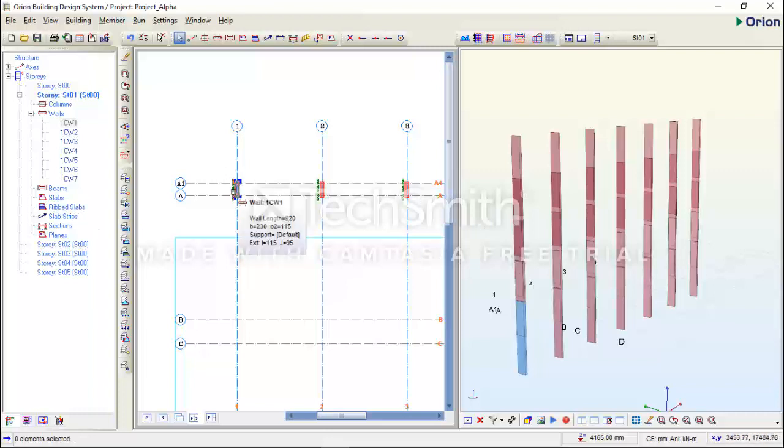So as I'm inserting my column, I'm not only inserting it for story 0 and story 1, I'm also inserting for the others. Why is it like this? It's because as I insert a column, Orion copies this column information to story 2, 3, 4, 5. You will notice a bracket in front of story 1, ST00. In front of story 2, you also notice ST00.